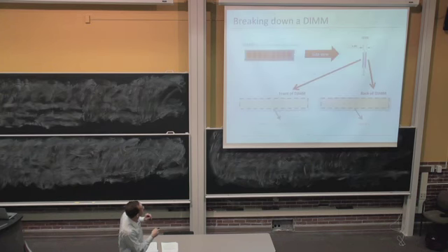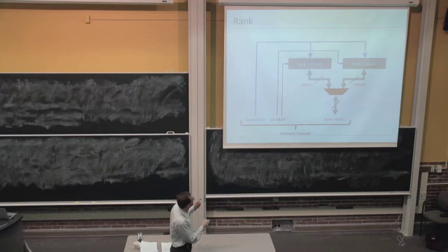So this is rank 0, rank 1. Well, this is one thing I did not talk about. Essentially, rank 0 and rank 1 also share the buses. Well, they don't share the bus, but the bus is multiplexed across rank 0 and rank 1. So you can access the ranks in parallel. This is the memory channel: address, chip select, data, and there should be a command here.